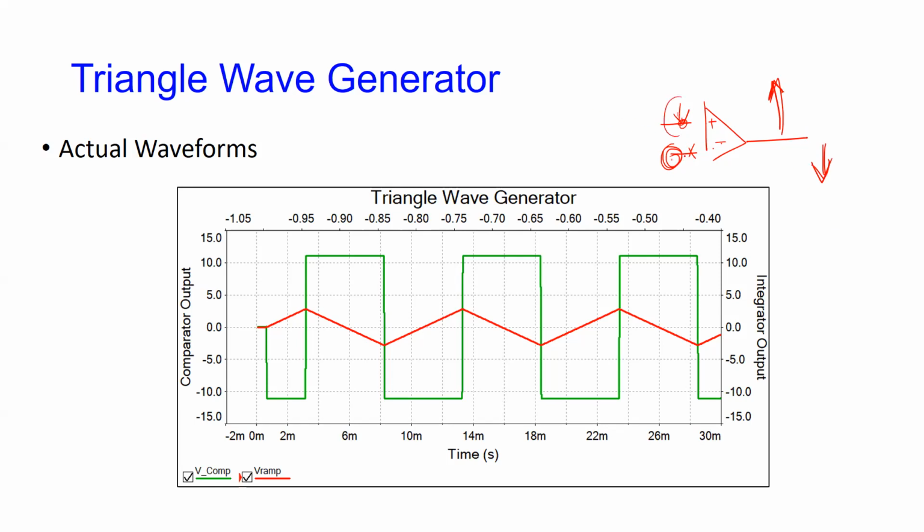This point now, I set this voltage with those 2 resistors, and here is a signal that starts to do this. As soon as it crosses some lower threshold here, the output toggles, feeds back, and integrates that and does this again for me. And it will just keep doing that once I have power applied to the circuit.